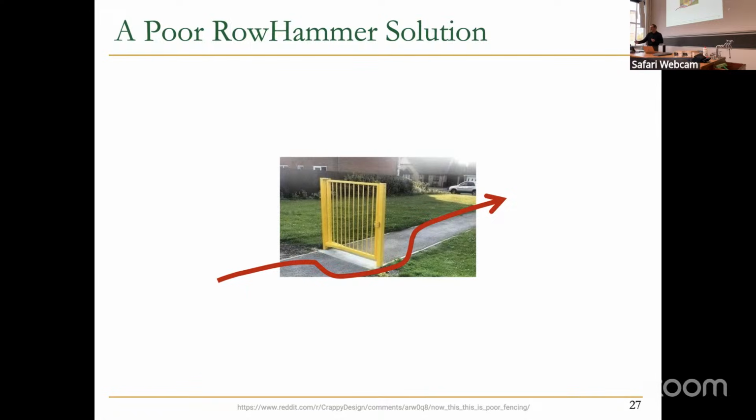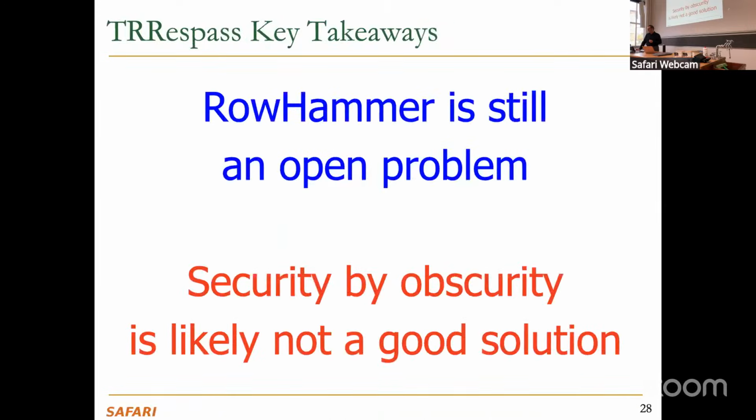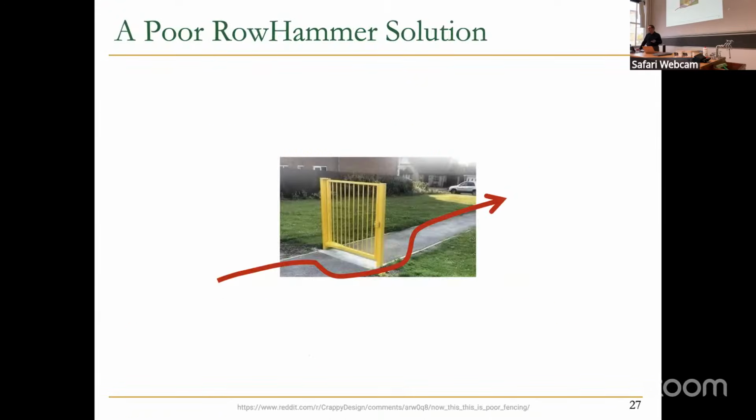So if you actually have not a good solution like this, then it's easy for other people who are smart to bypass your solutions, right? Okay. And sometimes they bypass it even in a benign application, right? Meaning your solution doesn't take into account some factors, and as a result, you actually have bit flips because your solution thinks that RowHammer happens after 4,000, let's say, activations, but you actually have a mechanism where RowHammer happens after 50 activations.